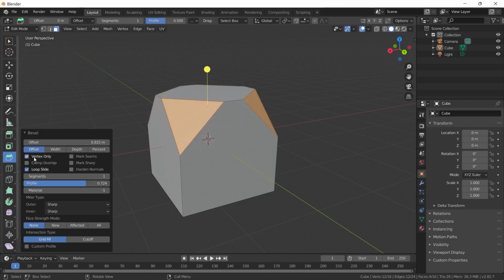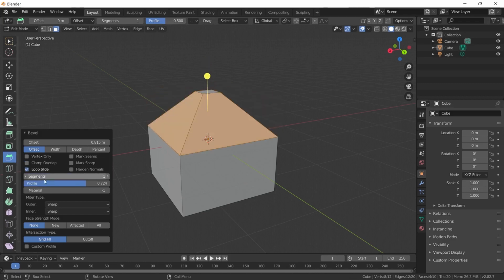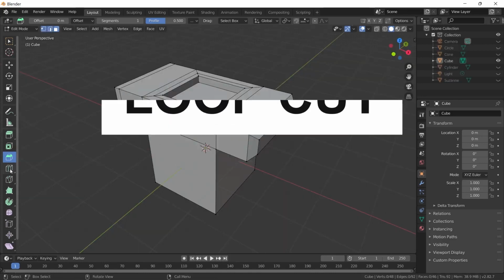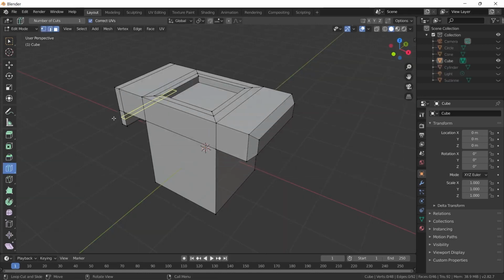When we check the vertex only option here, it will do this process based on the corners of the face. That is, the vertexes, not the face. Again, the panel here allows us to make similar edits. We can also do this operation, the vertex operation, as follows. We just pressed Ctrl B. Now I'm resetting these operations. This time I press Ctrl Shift B while face is selected. And so we can operate on the vertexes as if the vertex mark is marked. And again, you can decrease and increase the segments here with the mouse wheel.